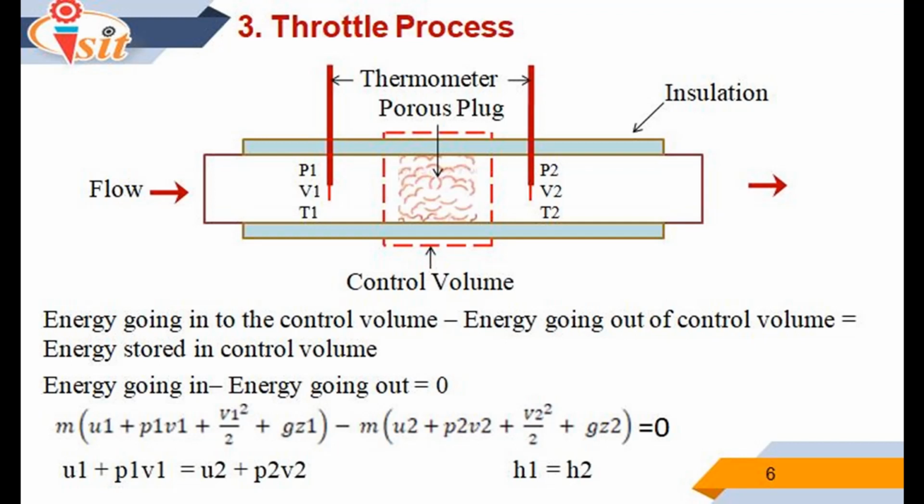But the steady flow energy equation is based on the assumption that the state of fluid at any point in the control volume is maintained the same. The mass going in is equal to the mass going out. Thus, there cannot be any energy stored in the control volume. For this case, energy going in minus energy going out is equal to 0.